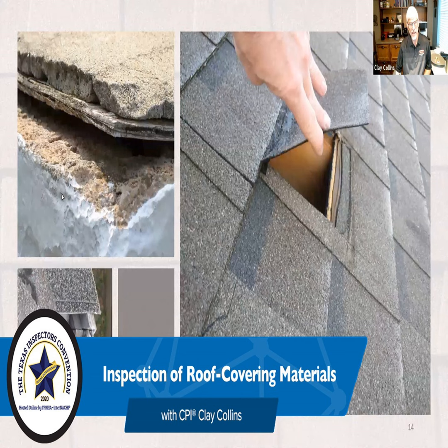Okay, another question came in if you would like one more. Sure. Are roof membrane materials better than tar felt paper? The tar isn't used anymore. That is an older product. And that's why I'm very careful to refer to an underlayment. You can call it a roofing felt. I would caution you not to call it tar paper. So an underlayment can be a roofing felt and it can be a synthetic.